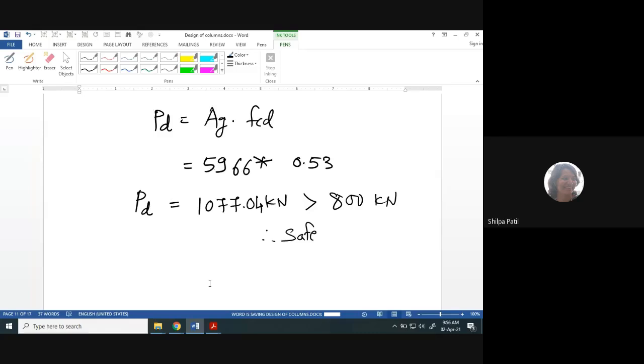So in case of industrial sheds also, when we do the analysis for footings, after designing the column you need to design the footing. For the footing also, when we consider the condition between column and footing, though it is fixed, we consider it as a hinged connection and do the analysis, because that becomes easy. If the connection between column and footing is considered fixed, our analysis will become complicated.